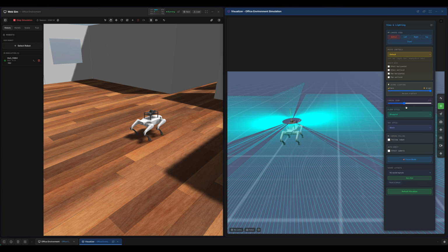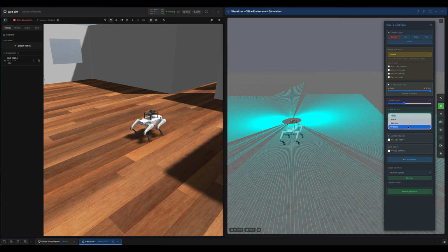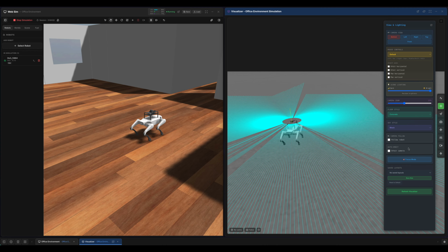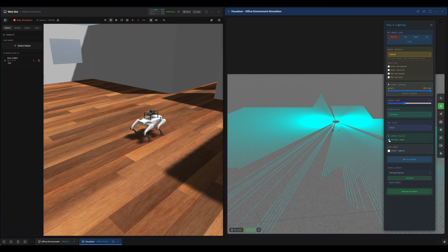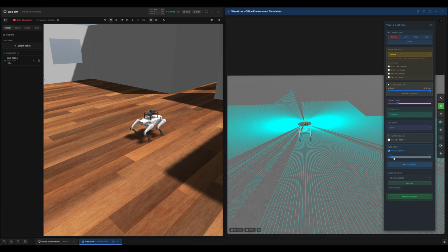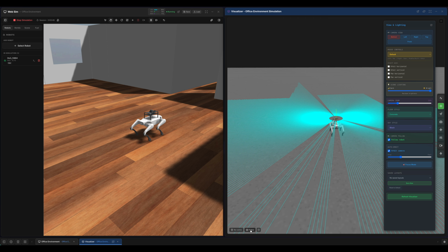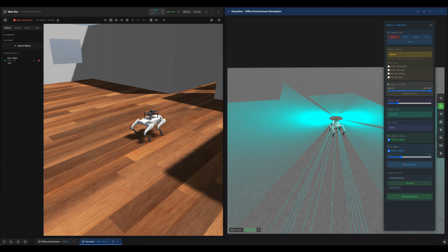You can explore these, and this will help you decide what shows up best with your robot, maybe the color of the meshes, etc. You can also choose whether it's dark, daylight, or it's just got effectively a black sky. And then there's another follow robot button in that space there. The orbit camera allows you to spin the robot on its own axis. It's quite good for demonstrations. And if you hit follow as well, that will center the robot to the screen.